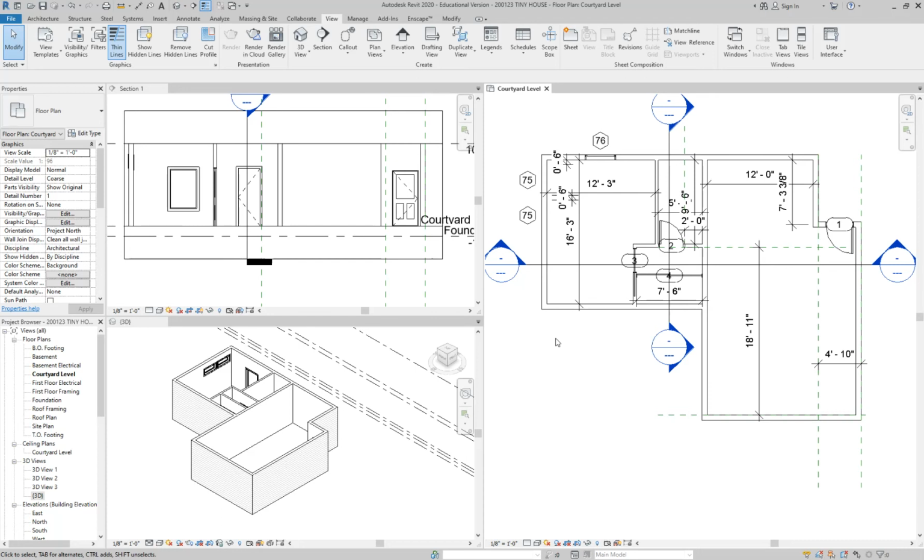So just remember your bounding box, or boundary, I think it's called the boundary. How do you spell boundary? B-O-U-N-D-A-R-Y. Thank you. There's no red squiggle up here to let me know I'm wrong. So your boundary box has to be one continuous segment. So what continuous means, no overlaps. And the next thing is start and end point have to be the same.